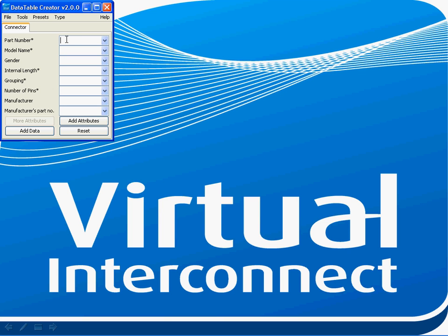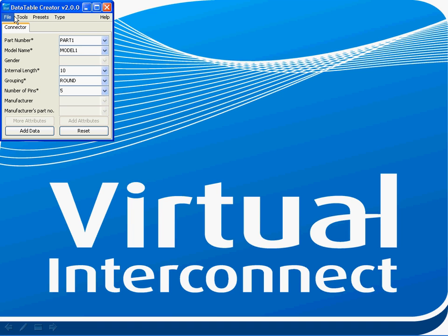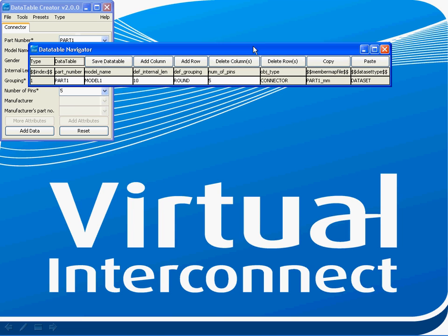We'll start by entering a part number, then a model name, then an internal length, select a grouping, and finally enter the number of pins. To complete the process, we click Add Data. We can now see that the top level data table has been correctly generated.